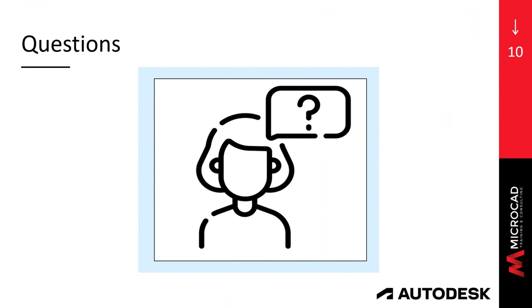While I am in Revit and very early on, I would grab building by building and send them out to Insight. And from very early on in the design, I would say from my schematic design, even if I'm just doing mass elements in Revit, I can send those to be analyzed in Insight and start making very educated decisions in terms of the location of my building within the site. Maybe I can rotate my building just a little bit towards the sun or away from the sun, depending on my location. And then those decisions being done in a very early design stage will ensure a much more comprehensive design at the end of the game.